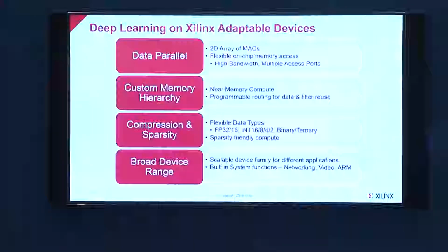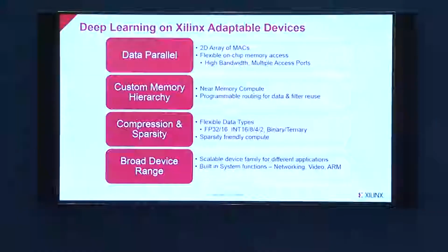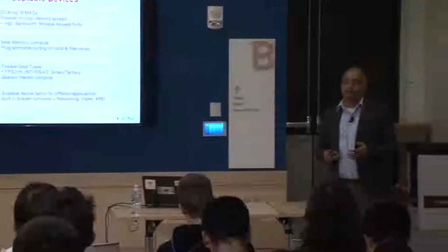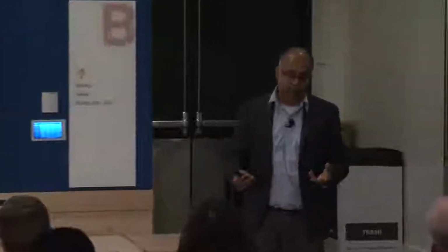The other is custom memory hierarchy. I did indicate to you that we have a lot of on-chip memory. And that on-chip memory, along with your ability to build custom memory controller architectures, lets you have a very customized memory hierarchy, which is suited to how you are going to implement your application.